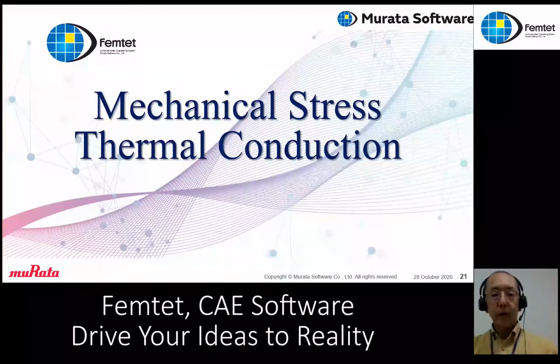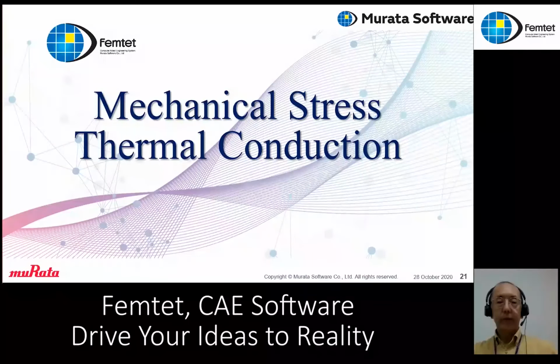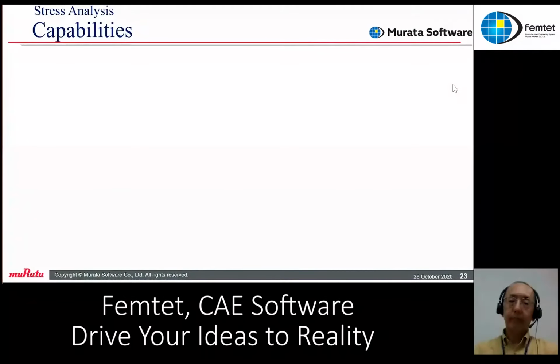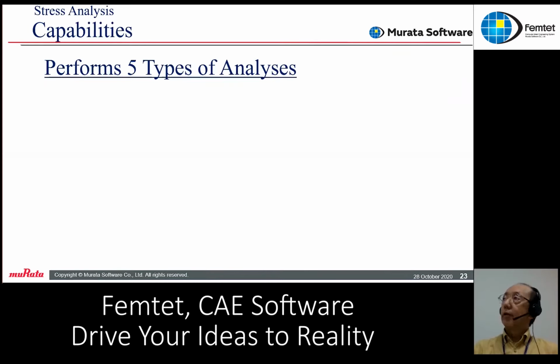Now, I'd like to give you the details of mechanical stress and thermal conduction. First, stress analysis. Capabilities of the stress solver. It performs 5 types of analyses: steady state, transient, resonant, harmonic, and buckling analysis.